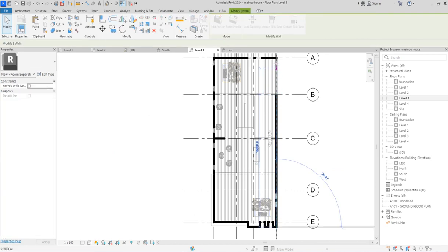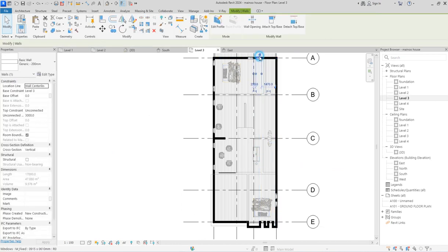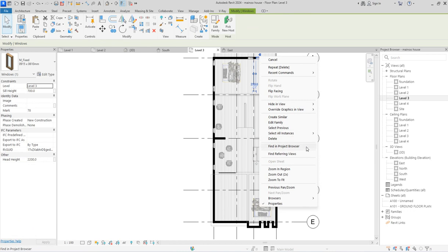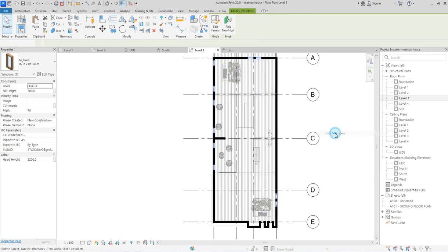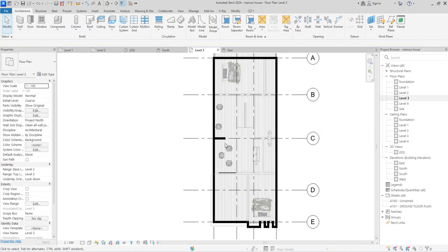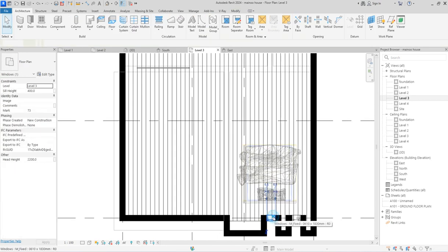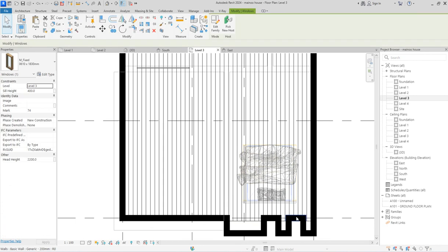And you push this to the loading. So what you do is select all instance, that's all the window. Select all the instance in this view, then click delete, everything will be good. So they are gone. So the same thing here, delete, and at the same time delete.